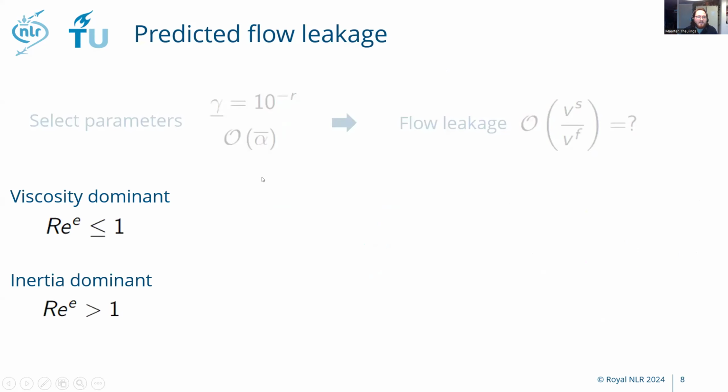Okay, so then I found that I need to have a different maximum penalization alpha, whether viscosity or inertia is dominant. So when viscosity is dominant, I set it like this, and when inertia is dominant, like this. The important thing to see here is that I'm manipulating the magnitude with this 10 to the power of q term. That becomes the parameter that I select, the 10 to the power of q, and all the other ones are just mesh parameters or material parameters I define in my problem.